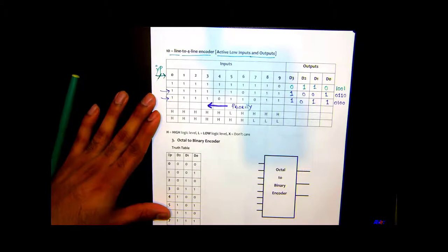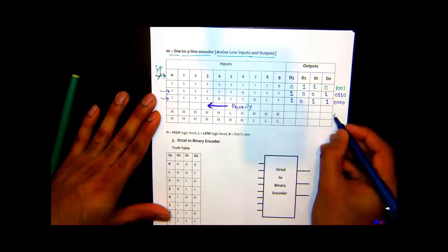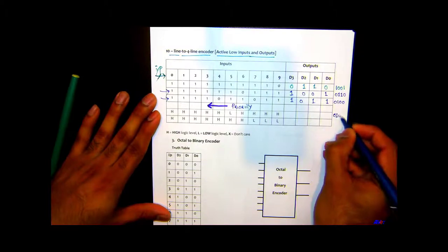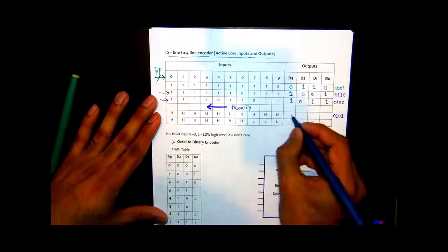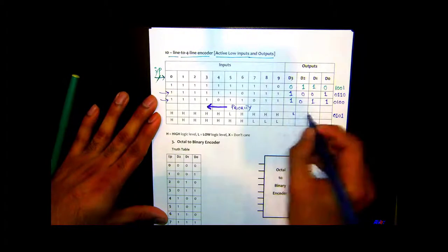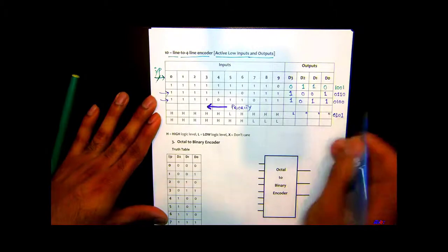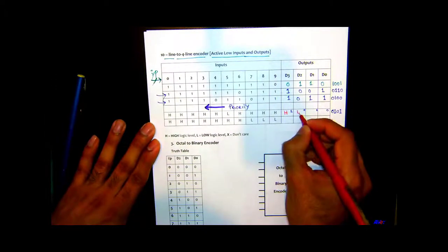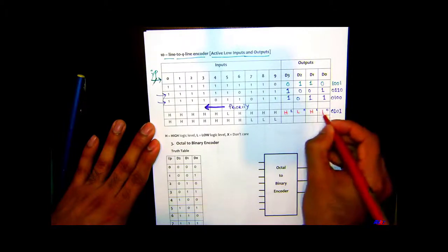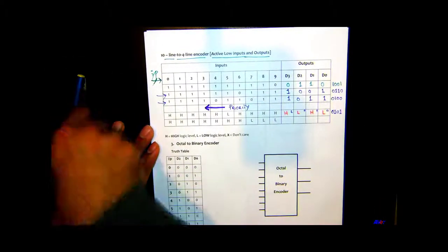Okay. We know that the 4-bit code for 5 is what? 0101, right? We are going to invert this, right? So it will come down as 1010. Okay. 1 is high, 0 is low. So it will be HL, HL. Okay. All right.